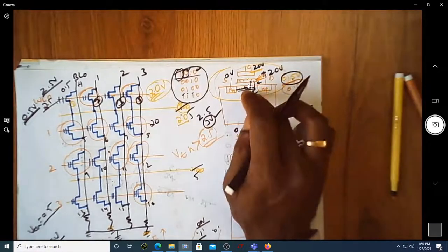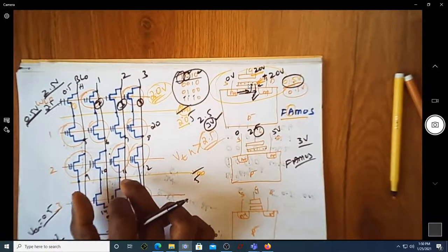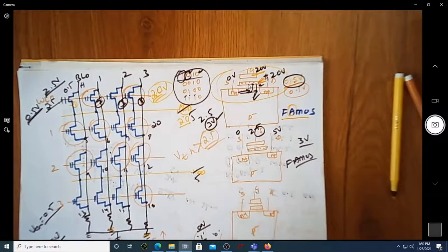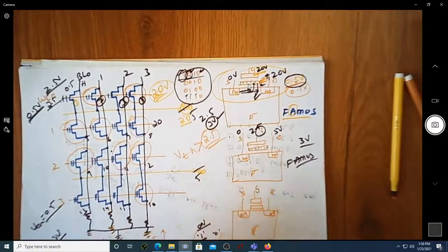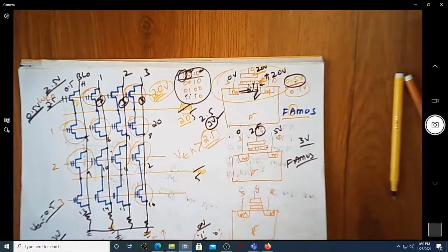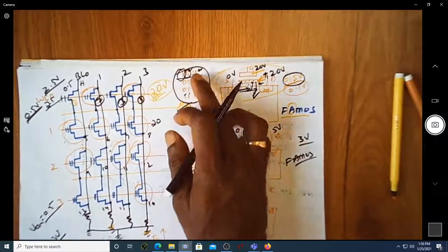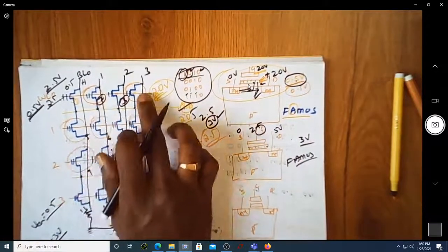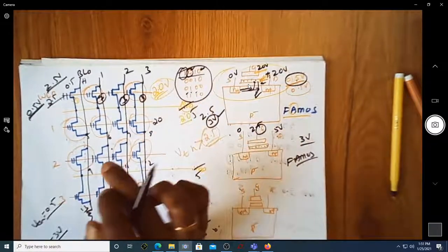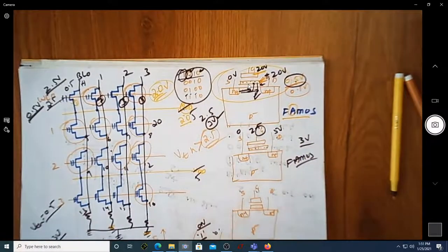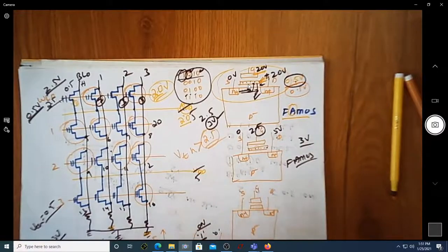So by exposing the ROM for a sufficient period under UV light, we can make all the transistors have 0.5 as the threshold voltage. Wherever you want to make changes, you just make the similar type of enhancement of that particular transistor to store a 0, then you can reuse the same memory array for some other application.